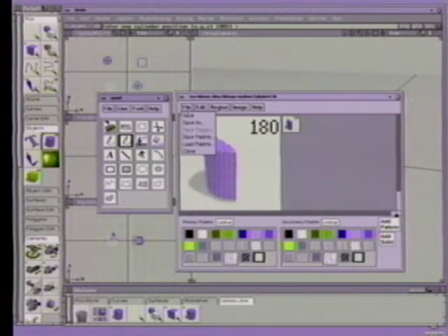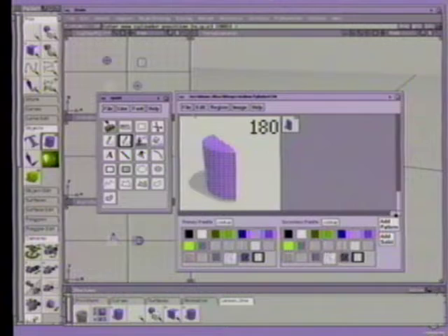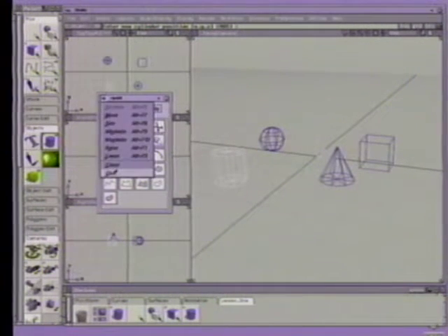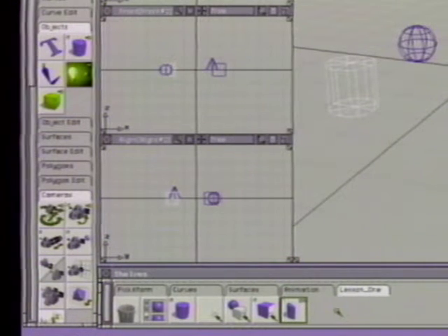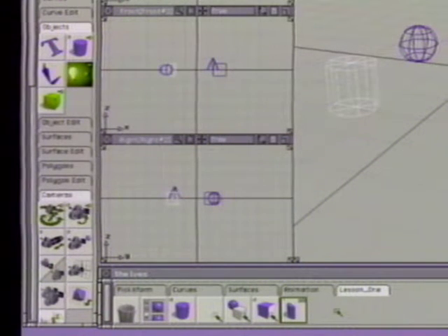When you have finished, choose Save As from the Xpaint file menu. Make sure that you choose SGI format from the Xpaint file browser and click OK. Close Xpaint and its tool palette. Back in the tool shelf, click on the icon and it will be updated to display the results. This editing process can be applied to any icon that is on the tool shelf. The tools in the tool palette cannot be edited using this method.